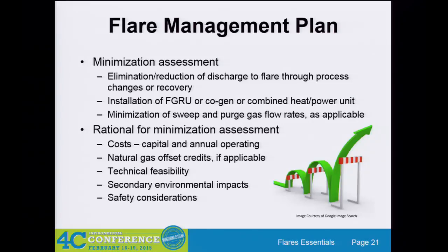When you're doing this rationale for your minimization assessment, you're told to consider these things. Usually cost is the one that'll get you out of a lot of things, especially flare gas recovery. A facility says, well, we have excess gas, but it's not a lot. And sure enough, you look with their flow meter and you're like, well, yeah, it's a payback period of 20 years. Well, yeah, you're probably not going to install that flare gas recovery unit.